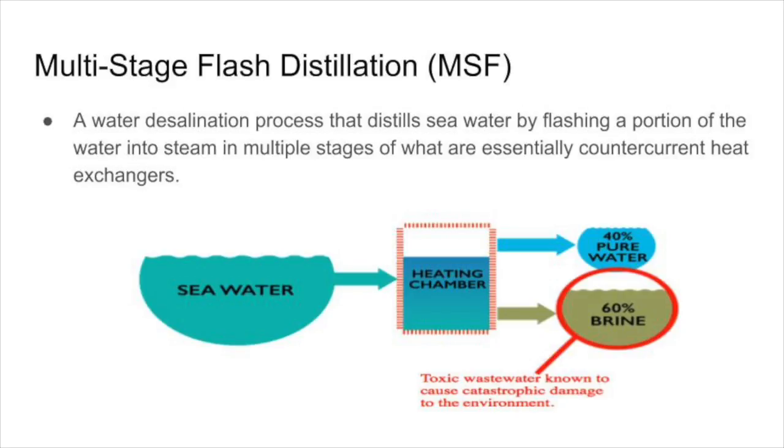The development of the MSF process occurred in 1956 through 1958. It has been used by many industrial companies to provide fresh and pure water to the most arid places in the world. In MSF, seawater vaporization takes place at low temperatures and vacuums. The vapors condense to form fresh water. At vacuum pressures, the boiling point of water is low, requiring less energy. A brine heater heats the seawater to around 90 to 100 degrees Celsius.